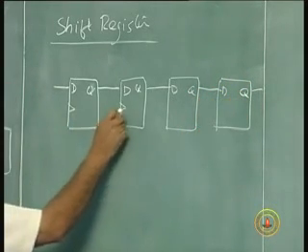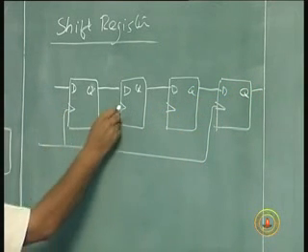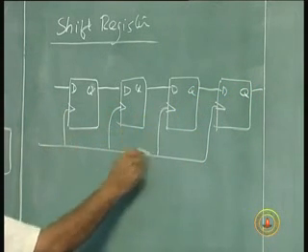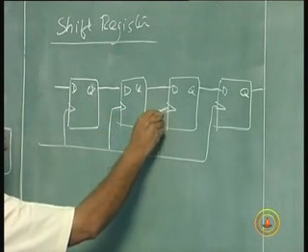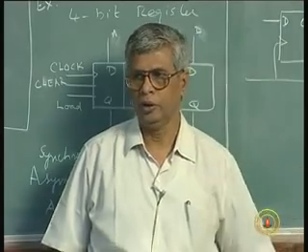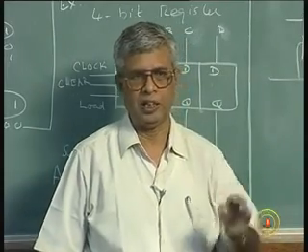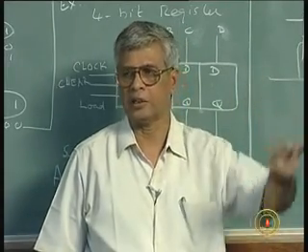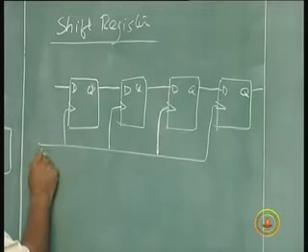Of course, I clock them synchronously. Here afterwards, unless I specifically say it is asynchronous or a ripple counter, we'll use synchronous counters, where clock is applied to all the flip-flops at the same time. When we need to use a ripple counter, I will specifically tell you it's an asynchronous counter or a ripple counter. So this is my clock.